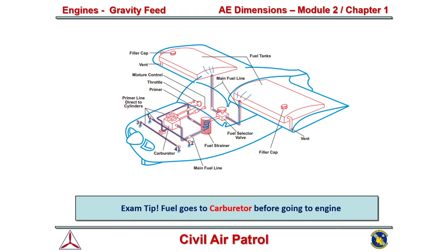One important thing here I do want to talk about for those of you that are looking to learn how to fly is that fuel selector valve. Super important. If you're in a Cessna, you can set it to both, and then you don't have to worry about it again. If you're in a Piper or some type of other aircraft where you have to make a left or right selection, you want to make sure you don't forget about that. You want to make sure you have good management of that.